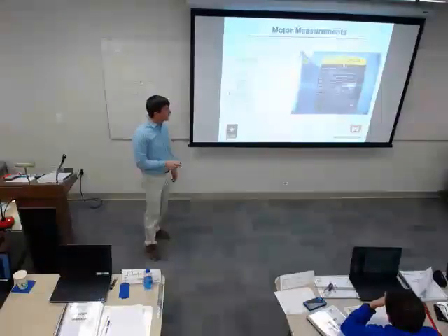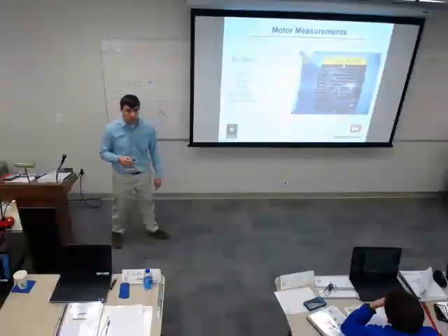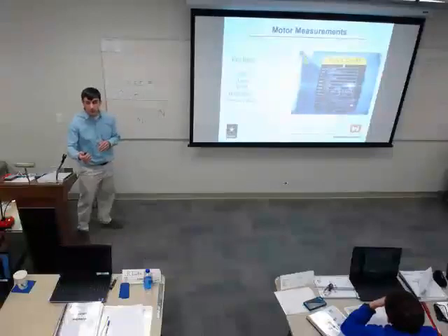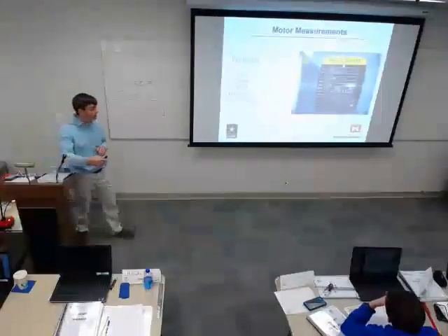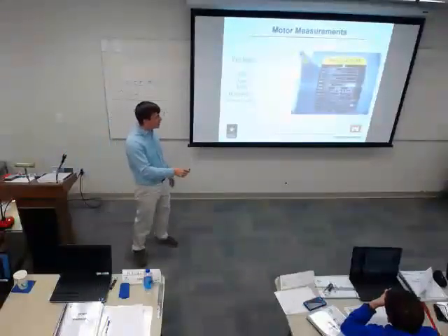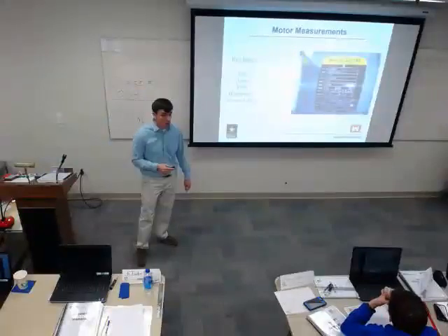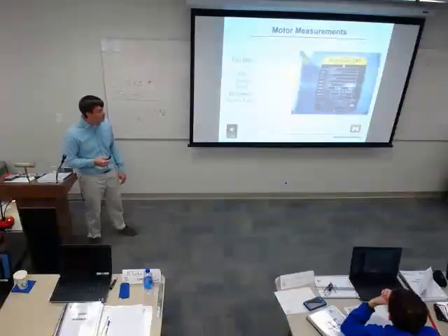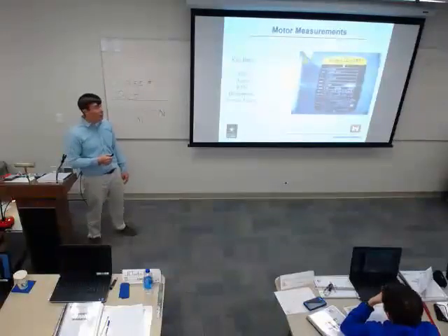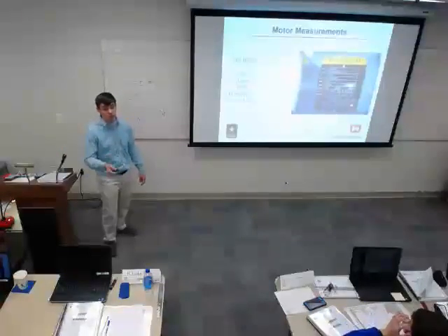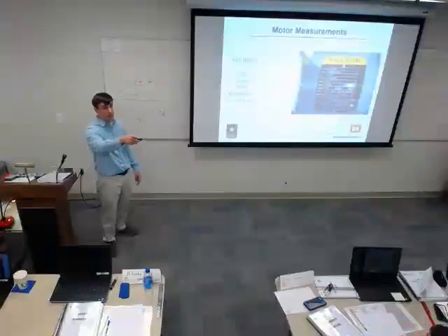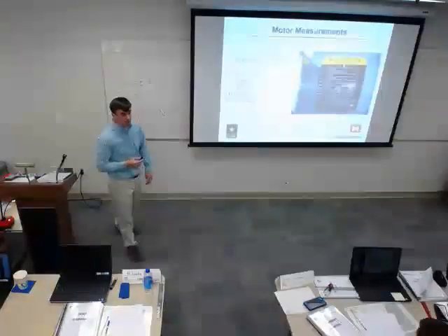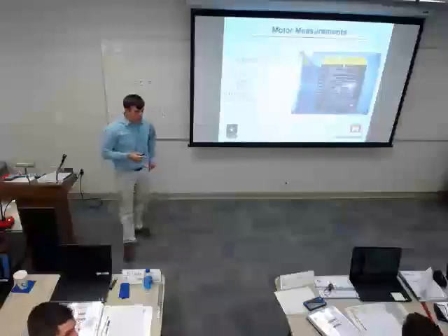This motor is rated for 1725 RPM, but I can attach whatever size sheave I want to it and get a different RPM on my fan. Most of the time, our specs are going to call for a 1700 RPM motor. You could put a larger one in. You could do 3600, but noise can be a consideration if you start getting the larger motors that are spinning faster. On these, also in 3-phase, we get all the measurements from all 3 phases.